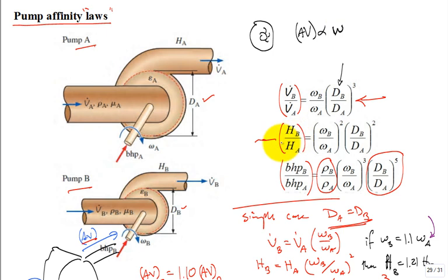It's kinetic energy coming off the tips of those impellers. Isn't it rotational speed? Then you have the omega squared. So the head is proportional to omega squared. Okay? It's the kinetic energy which is related to the rotational speed and the outer diameter, so that velocity squared gives you omega squared.